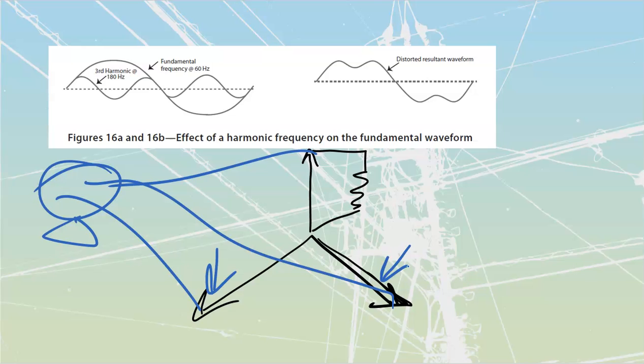So anytime you have large amounts of current that you're taking off just a single line like this, it would be better to break this load into three smaller parts. We'll make a baby load there, then take another baby load and stick it across here, and another baby load, stick it across here. Split it up, put it evenly across your components. It's one of the last checks that you're supposed to be doing on a job site before you leave anyway, just throwing your meter onto that panel and making sure all your phase currents are somewhat the same.